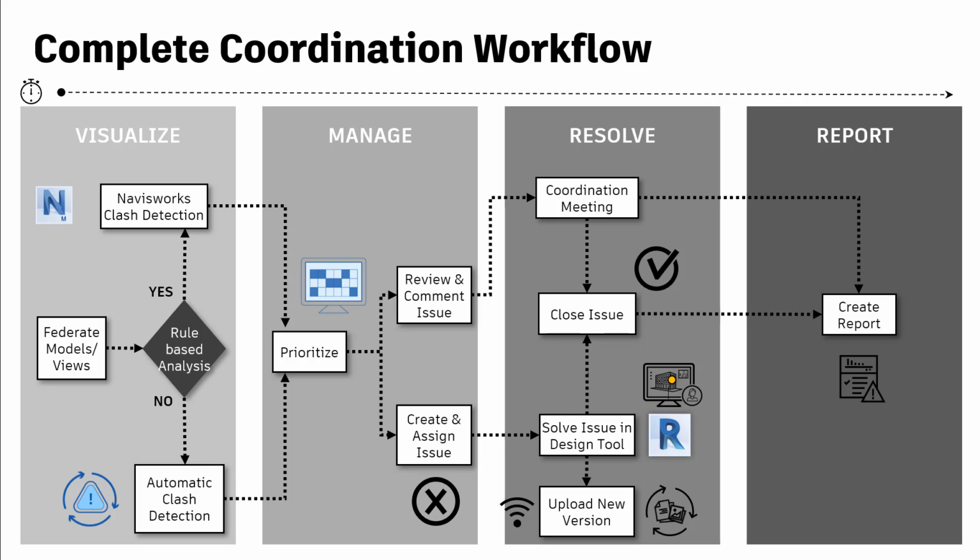Starting from the first steps of the process, design teams and trade constructors are already uploading their models to the CDE, sharing packages in design collaboration as we have seen before, where they can share and iterate their content. Model coordination monitors private coordination spaces for each trade and automatically aggregates the models and analyzes them for clashes, reporting the results in a clash matrix for review and prioritization by the trade coordinator and the design team.